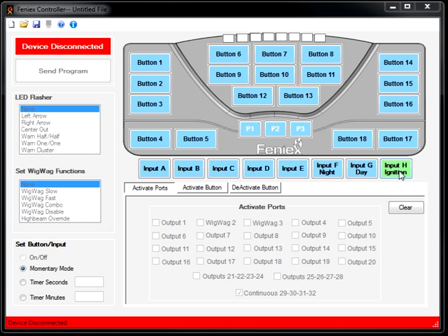If you wish to run the device without an ignition mode, then what you do in that case is simply tie 12 volt constant into input H, and you don't need to worry about ignition capability. In this case, I would like to keep an ignition mode and set a timer sequence. For the most part, I would like to have an additional 5 minutes whenever I power down my vehicle to have my controller illuminated and active in the event I need it for a quick situation.